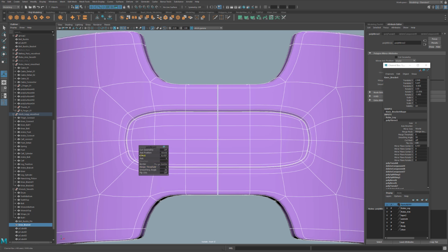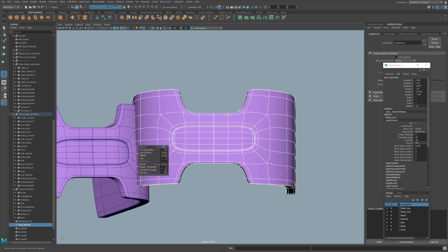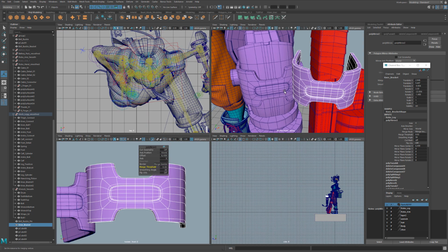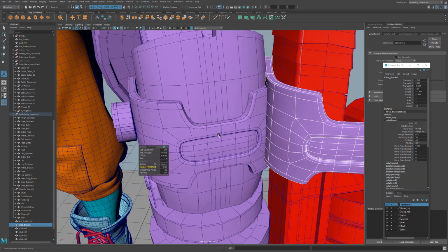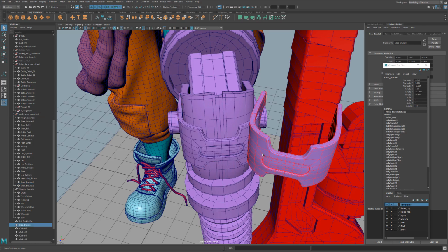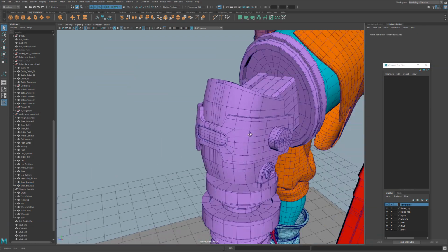And then once that offset is pretty much dead square in the middle, and I'm just holding down Control Shift just to get more gradual control, that looks pretty good. And now we could assign a low merge threshold. That's going to be mirrored exactly half. And now this is pretty much perfectly placed, and we didn't have to do anything to this. So we can go in here and delete this piece.